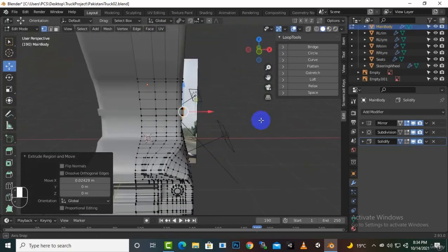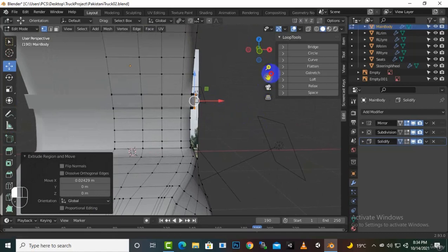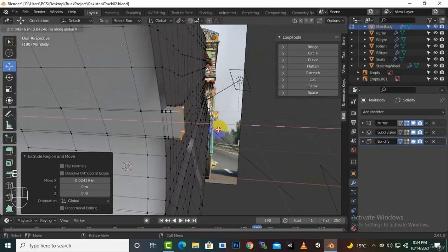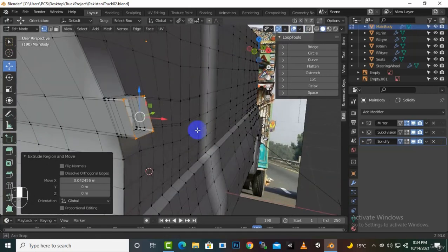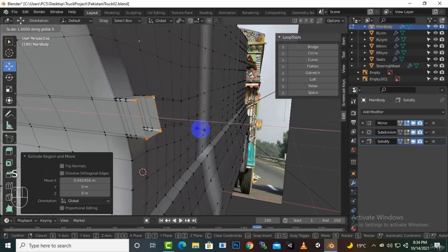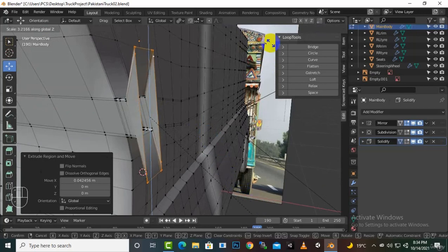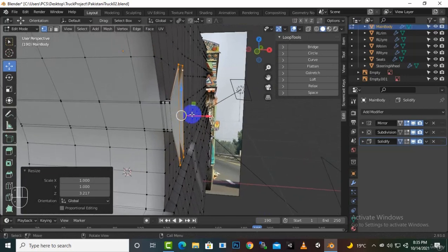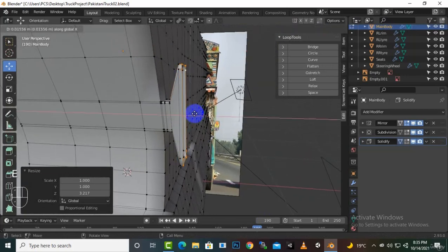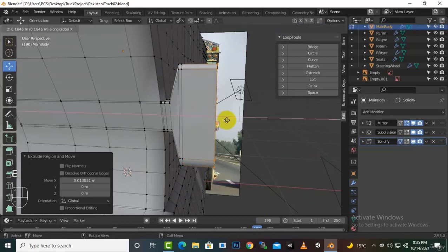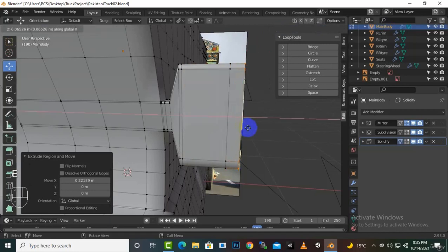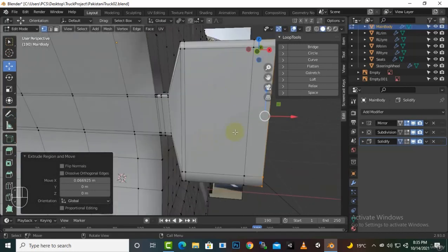And here you can see the size, and for the mirror usually the truck mirrors are quite big, so we'll just extrude it to x-axis a little bit more, and here we'll just scale it to z-axis, and we can scale it like this, maybe yeah, this much is good. And then we can just extrude it to x-axis, very small extrusion, then extrude it to x-axis, a bigger one, extrude it to x-axis, the bigger extrusion, I think yeah, this much is very nice.